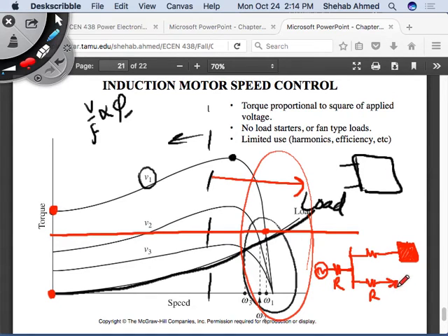If you draw a lot of current, then there will be a voltage drop across this resistor, a large voltage drop across this resistor. Okay, let's take the case where there's very little current. If there's very little current, then basically my supply voltage is reaching my loads. You agree? If there are no voltage drops, then my supply voltage is almost the same as the voltage at this node.